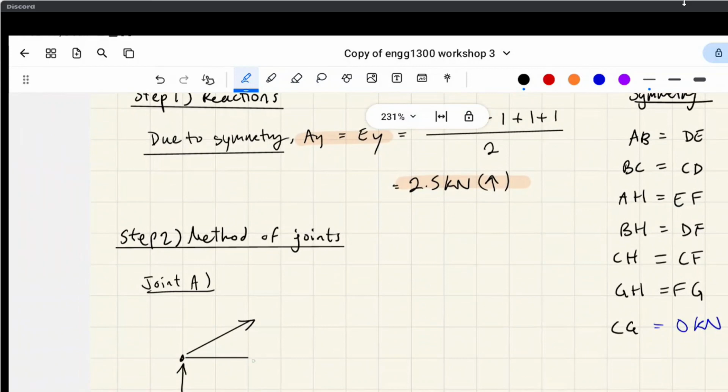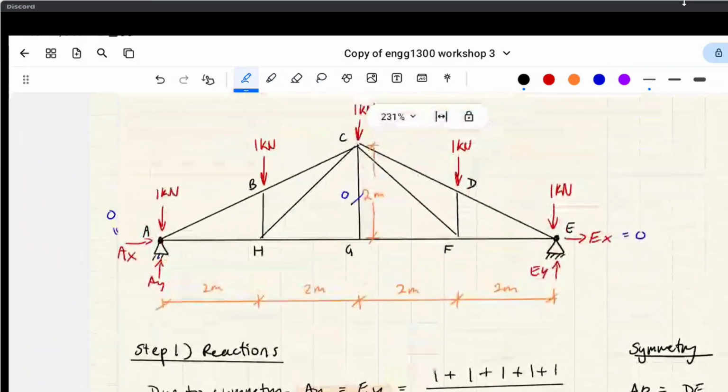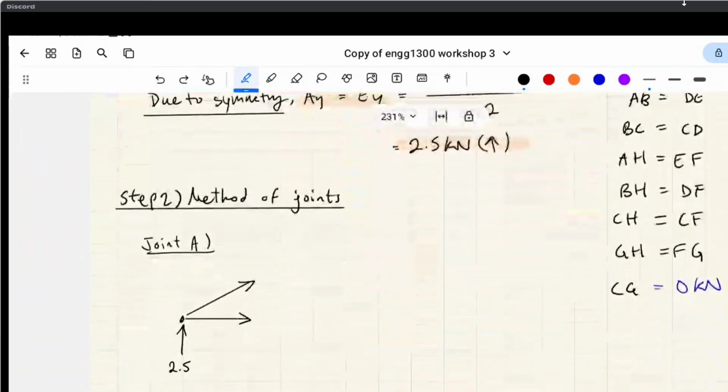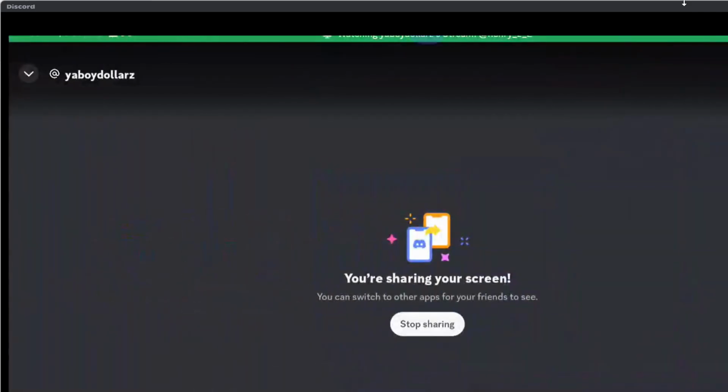There are all these forces coming off this one point. We're in particle equilibrium, so there are no moments happening. With the method of joints, we don't use sum of the moments. If you use that, you're not going to get any useful information out of it because all the forces are coming off the same point. You can use the moments for the entire system to solve for support reactions, but you can't use it when we're in particle equilibrium here.